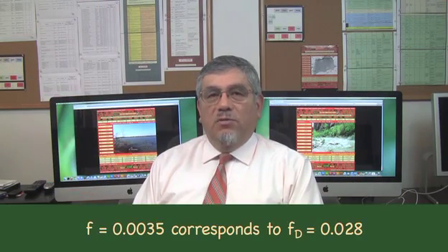the friction factor F varies normally in the range 0.002 to 0.005, which corresponds with Darcy-Weisbach friction factors between 0.016 and 0.04. Here we assume a mid-range value of F equal to 0.0035, corresponding to F sub d equal to 0.028. The Froude criterion reduces to